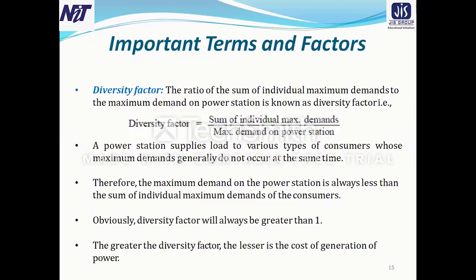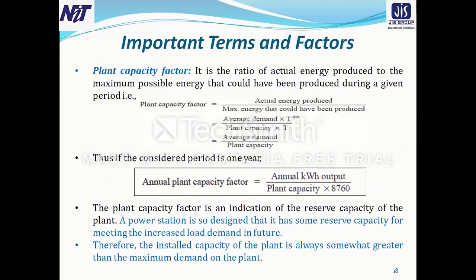And finally, we can say that the greater the diversity factor, the lesser is the cost of generation of power. So, diversity factor also plays a very important role for power economics, generation economics. Next, plant capacity factor.